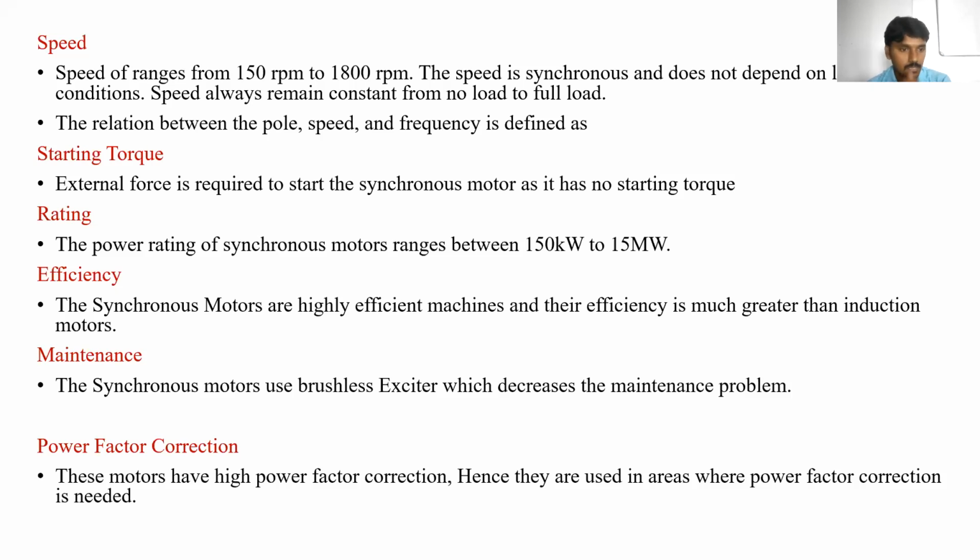Maintenance. The synchronous motor uses a brushless exciter, which decreases the maintenance problem. So here, in the case of a DC motor, we are using the commutator and brushes, but here we are not using any commutator and brushes. Due to this, maintenance obviously decreases.